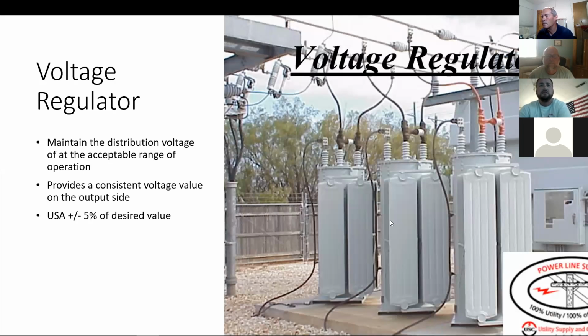Voltage regulators maintain the distribution voltage at the acceptable range of operation. Whatever you want the voltage to be, at least in America, it's going to be plus or minus 5% of the desired value, and it provides a consistent voltage value on the output side. While we're sitting on this picture, I don't know how old it is, but this is not allowed anymore. You'll notice that the regulators are mounted on a pad at ground level. I would say these are probably 6 to 8 feet tall. They now require more height in the air, so you won't see them mounted on a slab anymore. And it's a good safety thing.